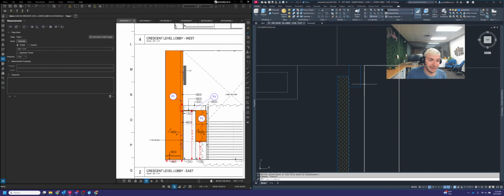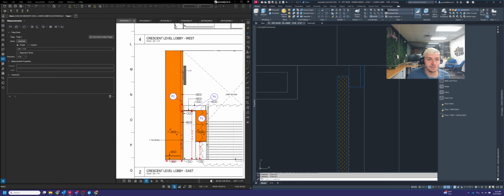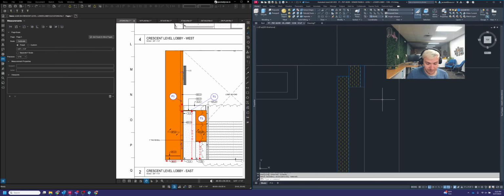So lining up with the back of your panel, lining up with the wall here. You're going to then have a little bit of shim behind that, and then we're going to hatch this here. Hatch, on the hatch layer, and we'll throw in some shim. Just a simple diagonal line through there is all you need.